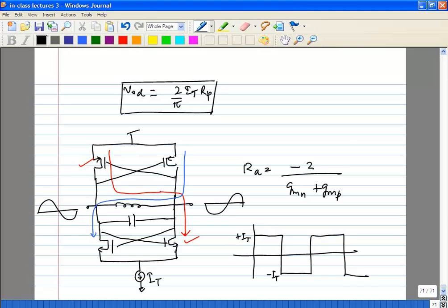And let us say of course that you have some RP, resistance of the tank. So obviously at resonance the inductor and capacitor impedances are going to cancel out and the current is actually going to flow through this RP, which is caused by the inductor. So effectively the current is actually flowing through the inductor.